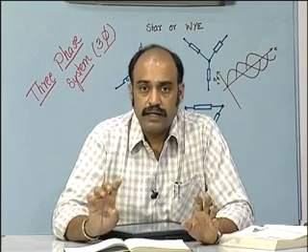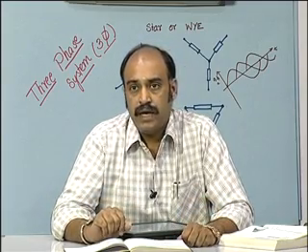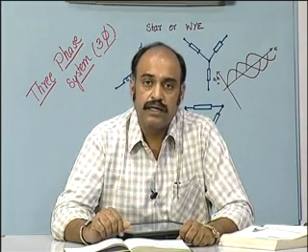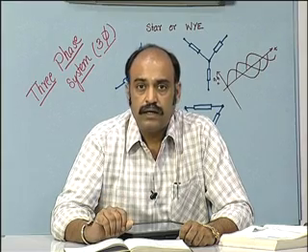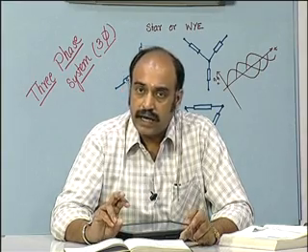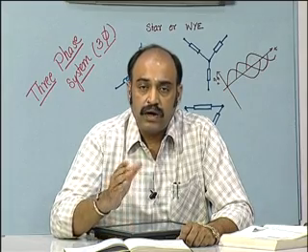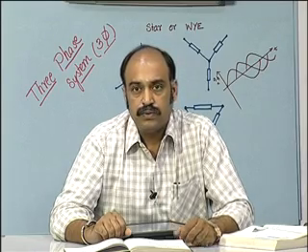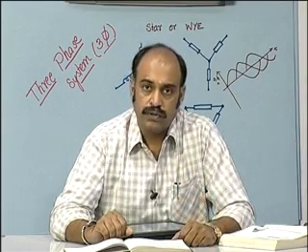This resistance, capacitance and inductance will form a delta, and these phase currents will cancel out in such a manner that there will only be the active component of the current. And on the line side, it will appear as though you have all three balanced currents flowing through it.